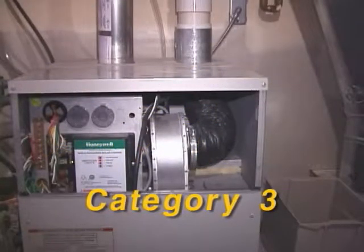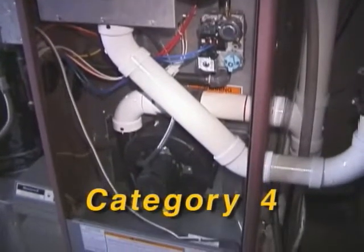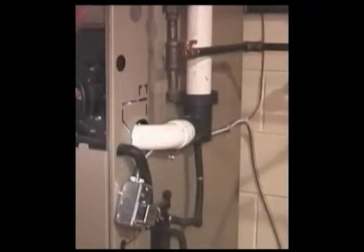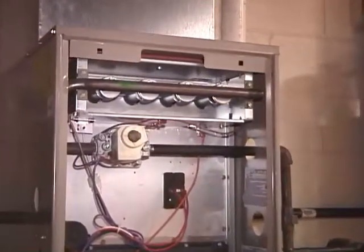Category 3 appliances use a fan to induce a positive pressure in the vent, but run hot enough that condensation in the vent is unlikely. Typical examples are sidewall direct vent water heaters and converted mid-efficiency fan-assisted furnaces. And Category 4 appliances use a fan to create a positive pressure in the vent, but run cool enough that vent condensation is likely. A typical example is a 90% condensing gas furnace. This example is a Category 4 furnace, but it is not sealed combustion. Here are the burners.